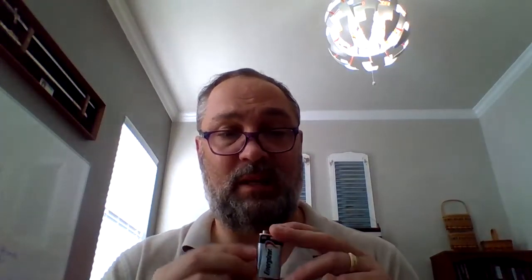And I'll tell you, if you handle a battery that has corrosion and you see it's split on the side and there's stuff oozing out, be very, very careful with that. Make sure you wash your hands, because one of the things you don't want to do is get it on your hand. Later, you're not thinking about it, you rub your eye or whatever, and now you've got battery acid in your eye. Very painful, and you'll have to wash it out, and you need to go to the emergency room very, very rapidly because your eyes are just too important.